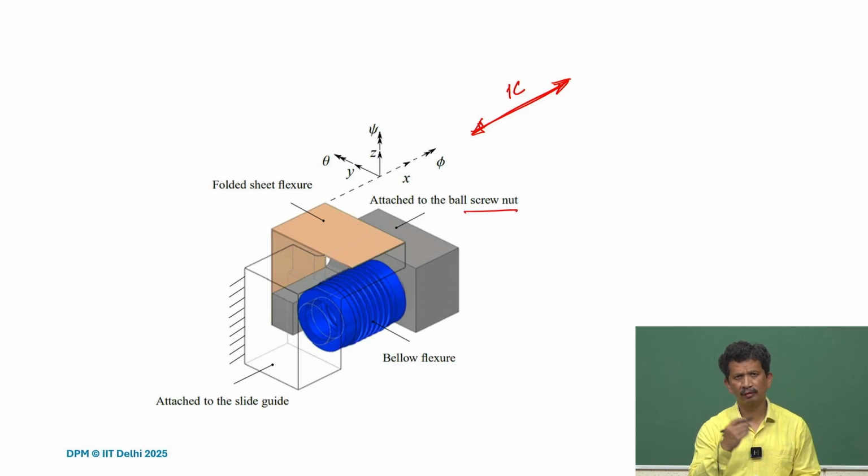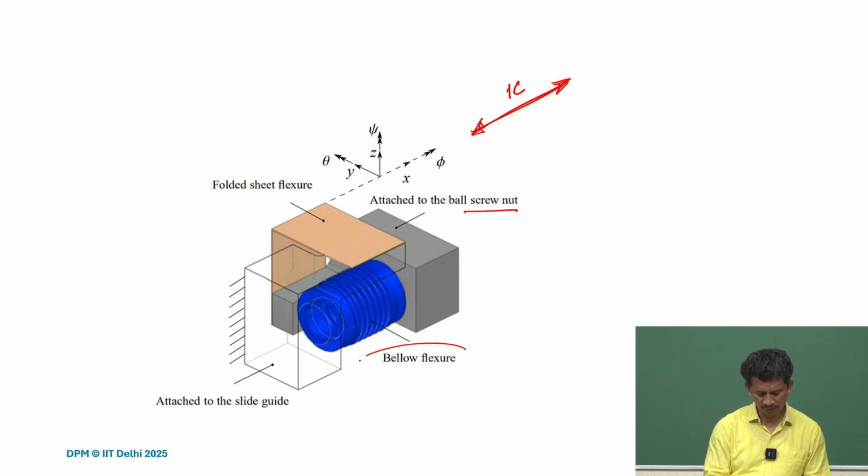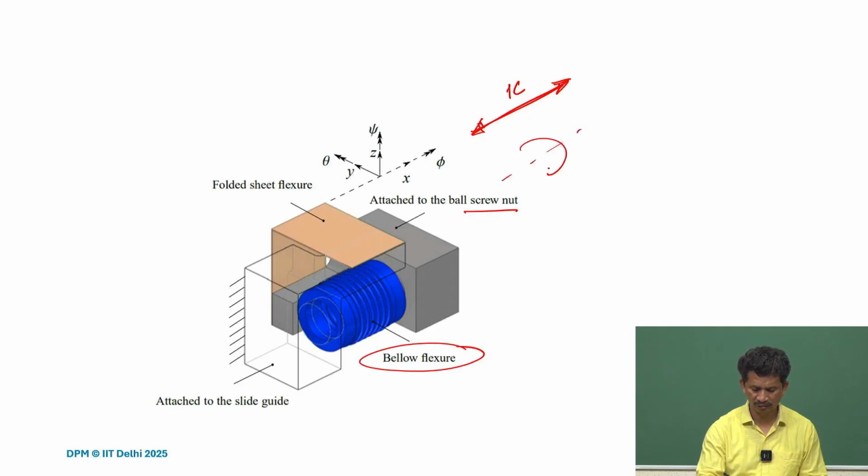So again, it's a screw, ball screw, the helical screw groove pattern what we have. If you look at it closely, it's only one DOF system. So the rotation and the translation is there, but then it's not independent. So for that, in order to constrain the rotation along the same direction, another constraint here, rotational constraints, and this is a translation constraint.